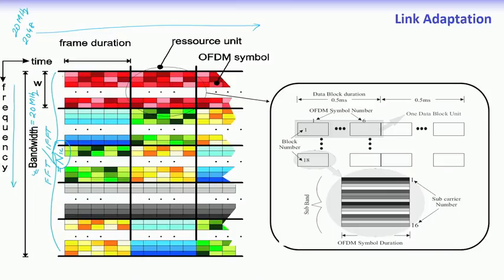And then each of these elements over here, this elemental width is the subcarrier spacing, which is obtained by dividing the corresponding bandwidth factor. So, I write it as F S indicating the upsampling factor divided by the number of subcarriers. So, one gets the subcarrier bandwidth, okay.